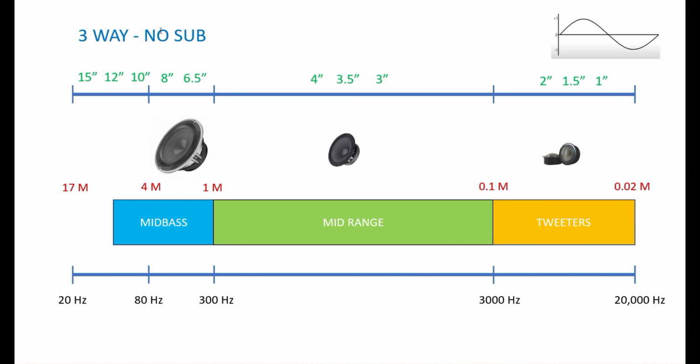But without a sub, it's going to be musical. It just won't have that super boomy low end, and you just have to be careful not to push your mid bass down too far, because it's going to reach the excursion limit, and if you do, it's going to sound boomy and terrible and distorted, and you're going to put your mid bass at risk of thermal damage.